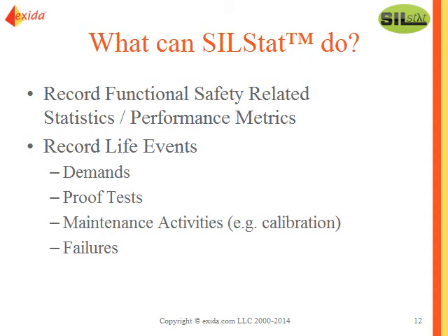gas sensors. Let's say an ammonia sensor. The actual sensor module will need to be replaced based on your specific conditions. If you're in a chicken farm, that may be needing to replace every 2 weeks. If you're outside in a normal plant, maybe 6 months. But there's a preventative maintenance that needs to be performed every so often.